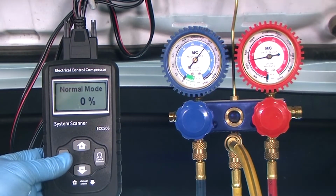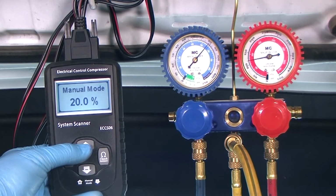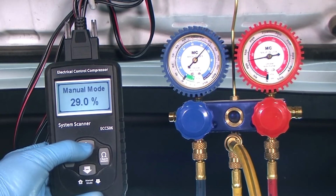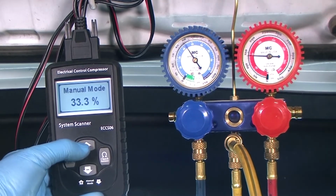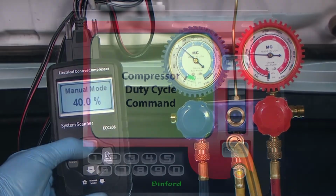So, by switching the tool to manual mode, we can take direct control of compressor pumping displacement and test the compressor and basic refrigeration circuit completely independently of the vehicle's computer. As we manually increase the duty cycle command, high side pressure should start to increase and low side pressure should drop. If we reduce the duty cycle command, pressures should start to reverse.